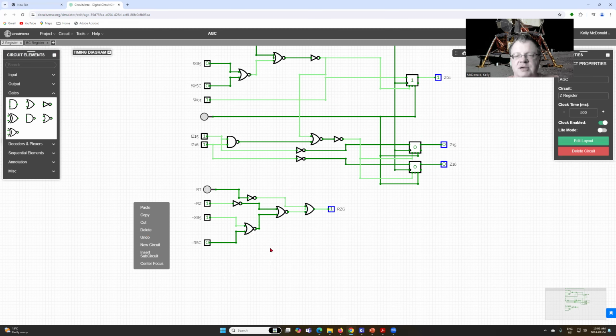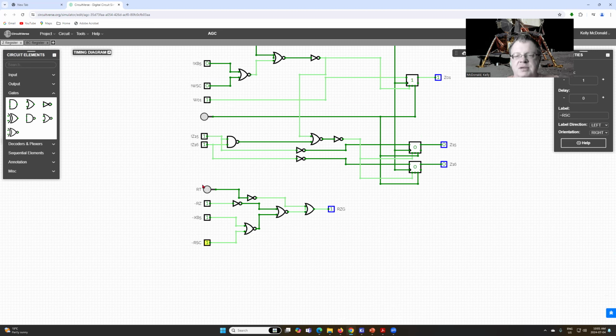And then our read circuitry, again, is very similar. We just bring in the write timer. But I can say if nothing has been asserted, I can see that we've got basically a 1 on the RZG signal, which means we're not going to enable the writing out onto the bus. But if I set this to 0 and click the write timer, we can see we're going to get a 0, which means chip enable, because the chip enable on the transceivers is negative logic. So that means it'll write data onto the bus.